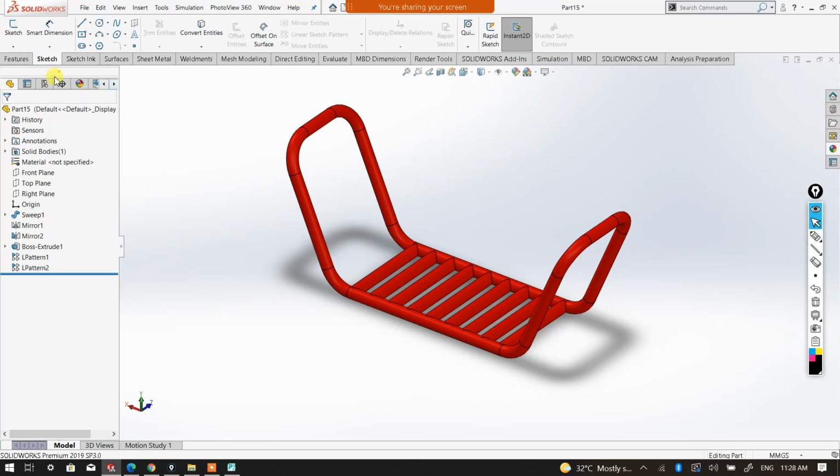However, for 3D sketch, at one time you can play around with three different planes, which is XY, YZ, as well as XZ. Okay. However, again, I will stress here for the normal sketch, at one time you can only implement one single plane. If XY, XY only. If XZ, XZ only. Then you have to exit from that particular sketch environment. If you want to work on the YZ plane with this 2D sketch, you can only play around with the YZ plane only. Okay, however for 3D sketch, at one time you can play around with all those three planes which I already explained to you just now, which is XY, XZ, as well as YZ.